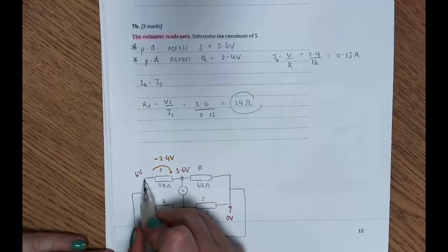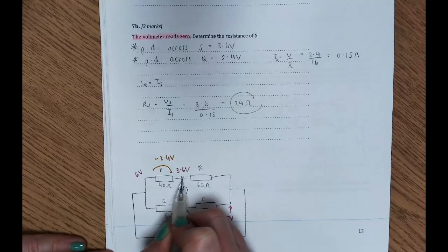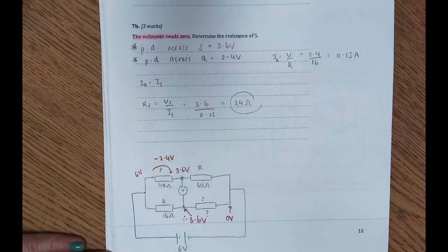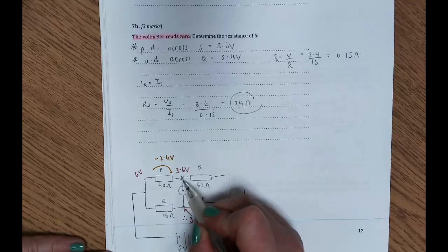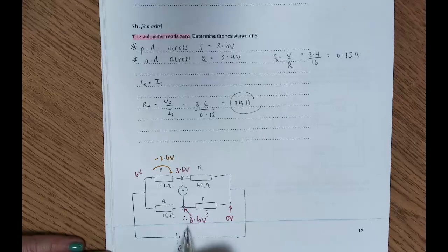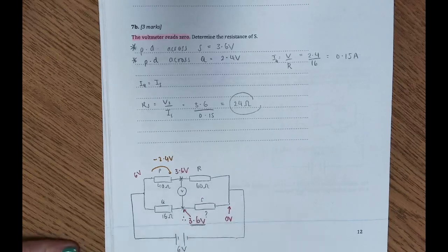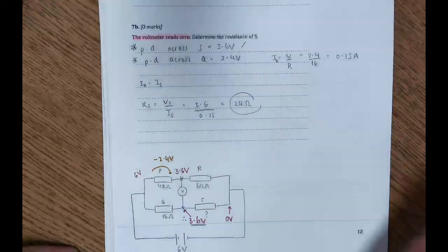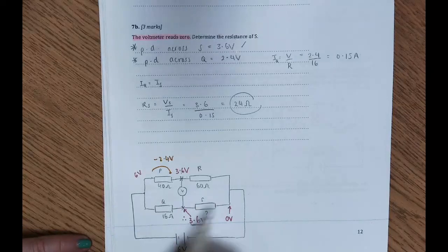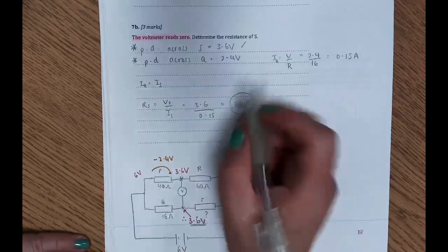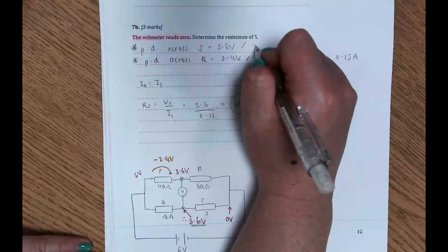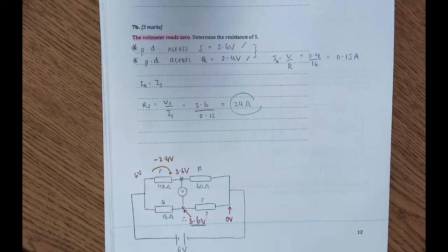Because we have recognised that we dropped 2.4 volts across here and therefore we're at a potential value of 3.6, it tells us that because we see a 0 difference between this point and this point in the circuit, this one must also be 3.6. That's what tells us 3.6 volts is the drop across S. Okay, so that's how we get this point. We know that 6 volts in total has to be transferred across QS, so we know that these two values have to add up to 6, so that's what gives us the value of the PD across Q.